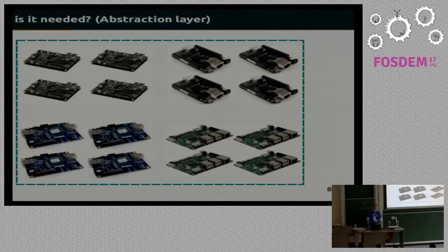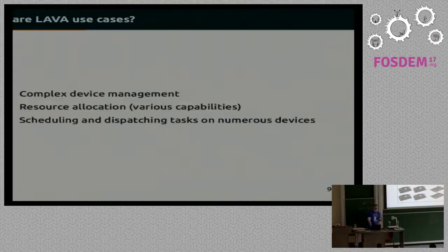Well, that's where Lava comes into place, because it provides an abstraction layer for the whole board farm. This way, all the complex device management is put onto Lava itself and is no longer your own task. Also, many different devices have various capabilities. It would be much easier if you don't have to worry about finding an actual device that supports all the capabilities you need for tests.